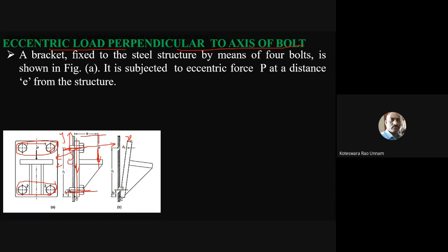The z axis is not the longitudinal axis. The longitudinal axis is nothing but the axis along the bolt. So this moment will create a bending moment. You can clearly see that because of the bending moment, it is tilting like this. So the two effects are direct shear stress and bending stress.